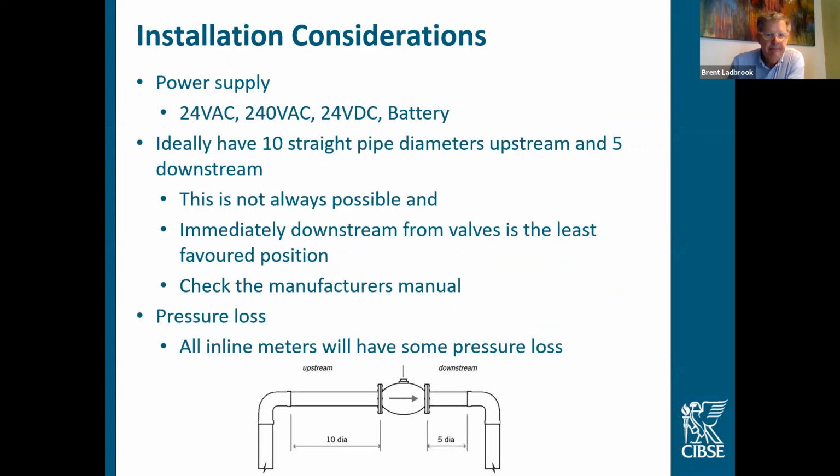Power supply, what power supply is available? Ideally have 10 straight diameters upstream, downstream, not always possible, as we said before.